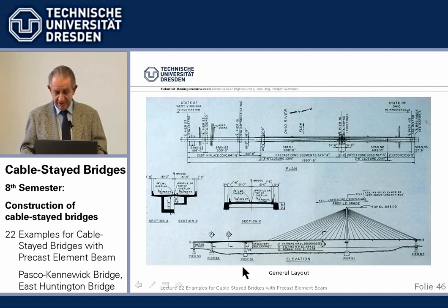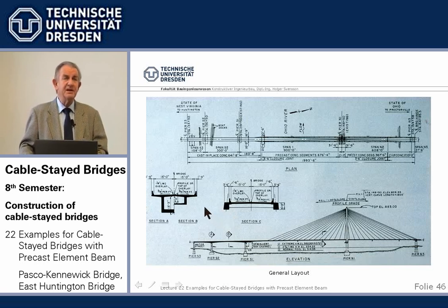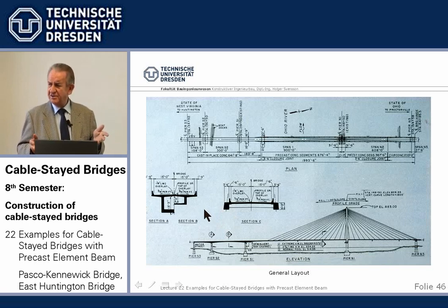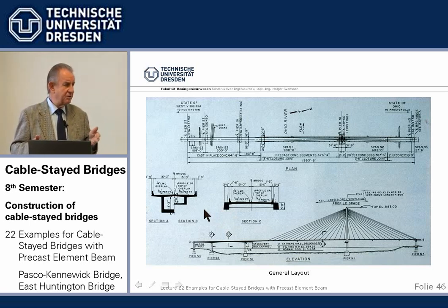Basically, that's the main pier, and these two piers were designed. And so we had to squeeze on here something which could be taken by the foundations. In concrete, what we did is, first of all, we used high-strength concrete, B65, at that time completely unknown in the US. Nothing to it today, but in 1978, unknown.